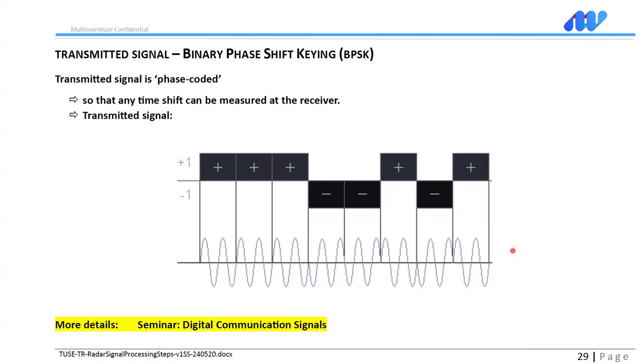And the basic idea of match filtering is to multiply the delayed version of this transmitted signal, as a reference, with the received signal and integrate. If, when you shift the transmitted signal, you hit the received signal at the right time, then the integral is going to give us a peak. It's going to be a perfect overlap with a larger number. And that's the whole idea. The match filter takes the original signal and finds its reflection, the delayed version of it. And once you get it, you get a peak.